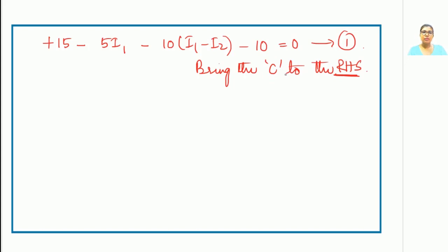Now there is an important part about this. Constant means no unknown variables associated with a particular number. Now will every equation have a constant associated with it? Not always. If a particular mesh considered by us has a voltage source in it, then there definitely will be a constant. If a particular mesh has no voltage sources, then your constant term will be 0.